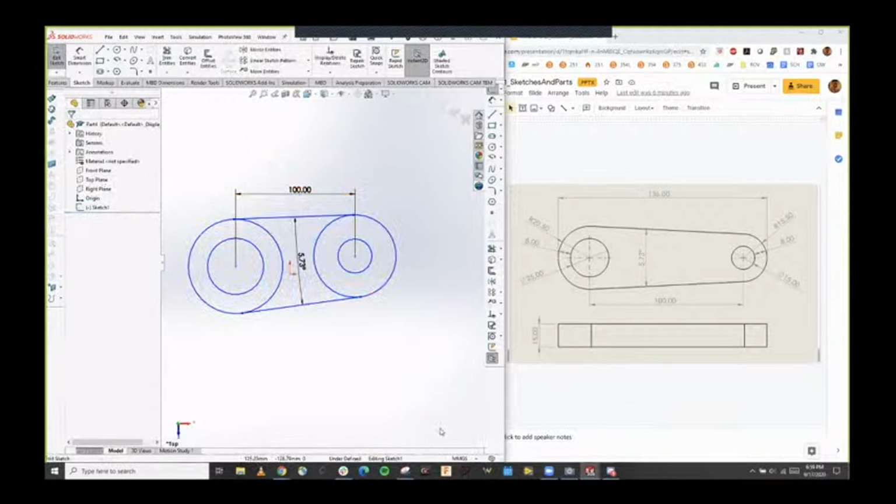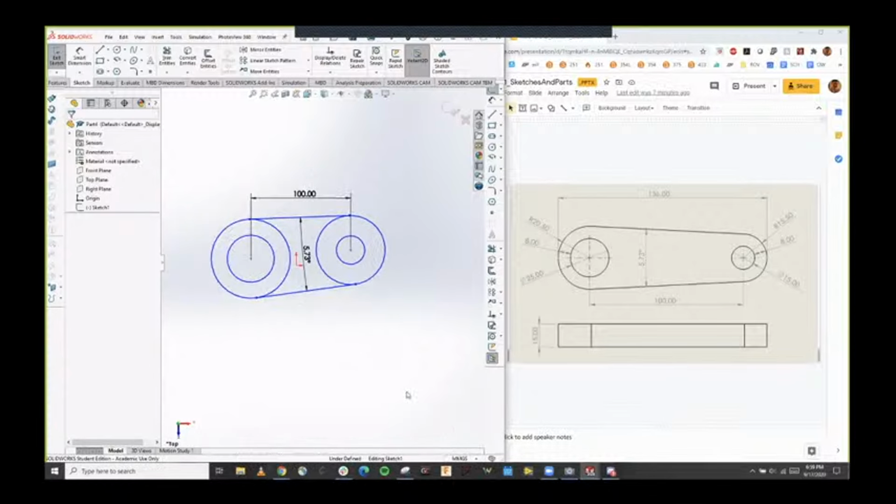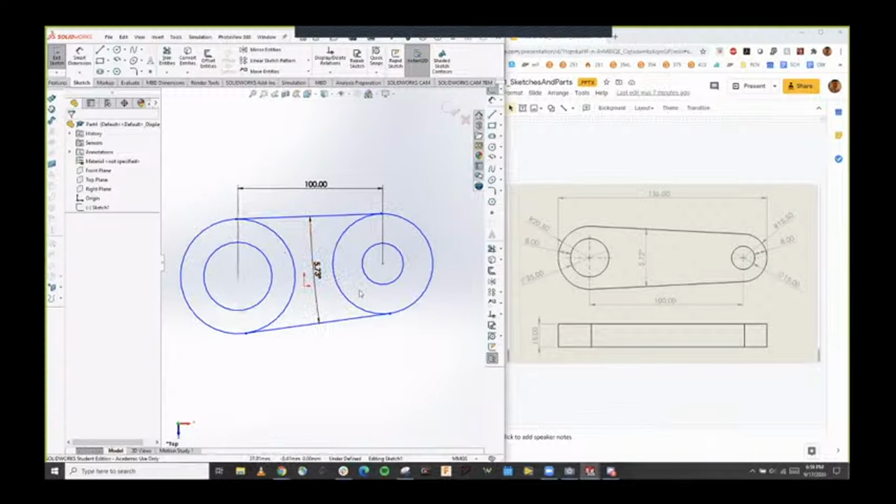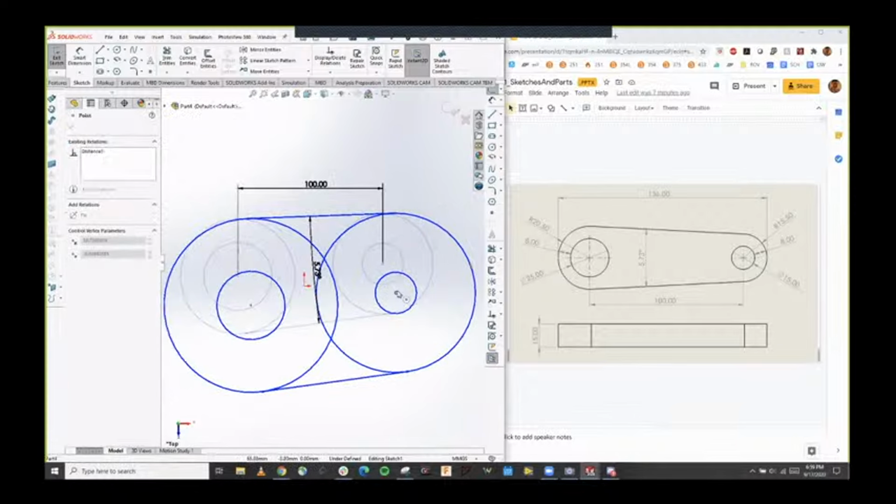All right, so what I just did there is where you can change the units of your sketch depending on what units you're in. You can hit this bar and you can be either in inch pound second, which is imperial units, millimeter gram second, or standard SI units, meter kilogram second. For smaller parts, we'll probably use millimeter gram second, since this is a small linkage, as you can see. But step one is to define this distance as the 100.